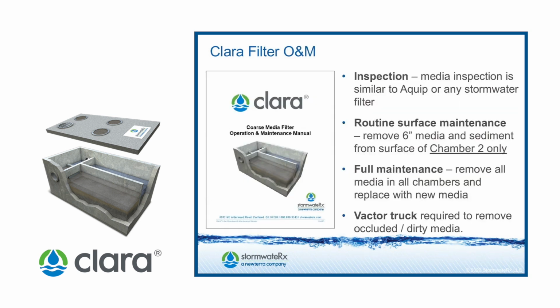My last slide addresses the O&M for the Clara filter. As with any BMP today, inspection and scheduled maintenance is critical for long-term operation, functionality, and pollutant removal. Inspection of the Clara filter is similar to our equipped filter. We would ask that you observe and note the level of TSS buildup on the filter surface in chamber 2.